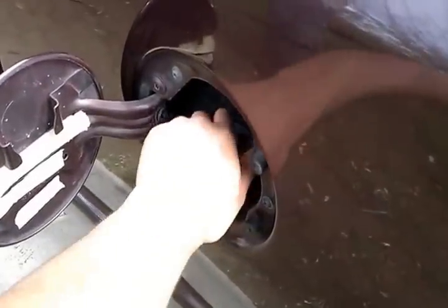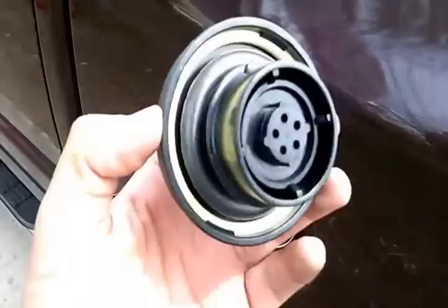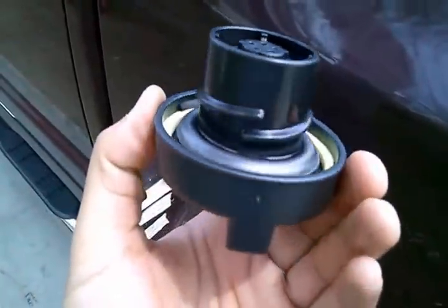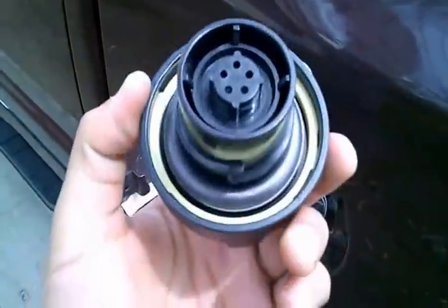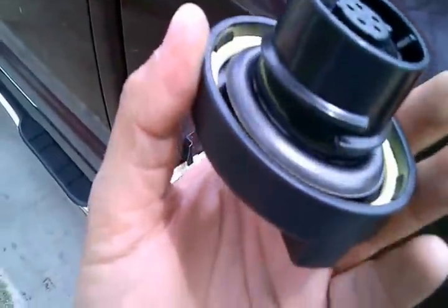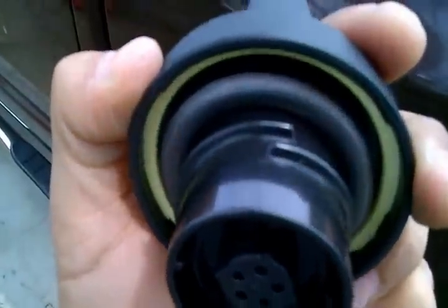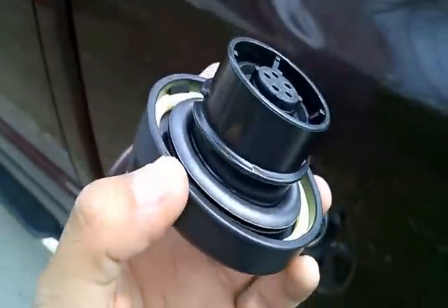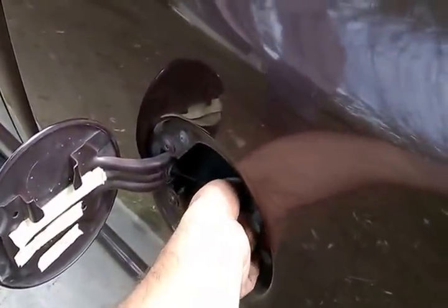So I'm here at the fuel tank's fuel cap. I'm going to start by doing a visual inspection on this fuel cap. It looks fairly new. I guess the customer did replace this fuel cap with a new one, because the seal looks in good condition. I don't see any cracks. I don't see any damage to this fuel cap. So for now, I'll say this fuel cap is not the cause of this P0456 small leak.